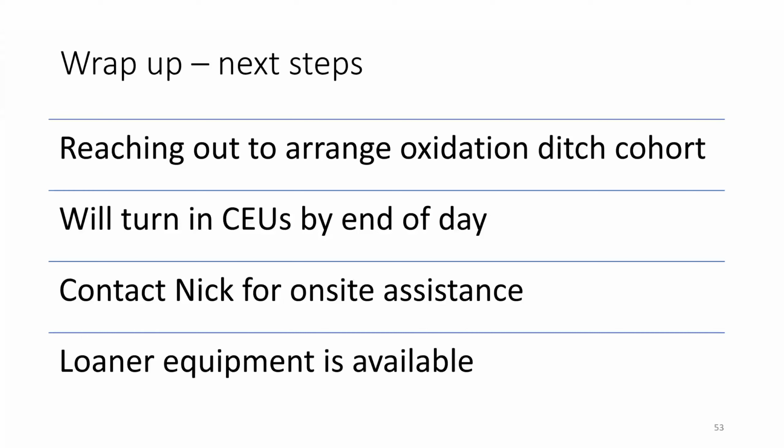I would also encourage looking for a spectrophotometer or photometer that can do the tests that you need and those that you might find interesting, and that can do tests where the reagents work and report within the range that you expect to see at your plant. So ammonia coming out of your clarifier is hopefully under 5 most times, so 0 to 5 would be good for that.